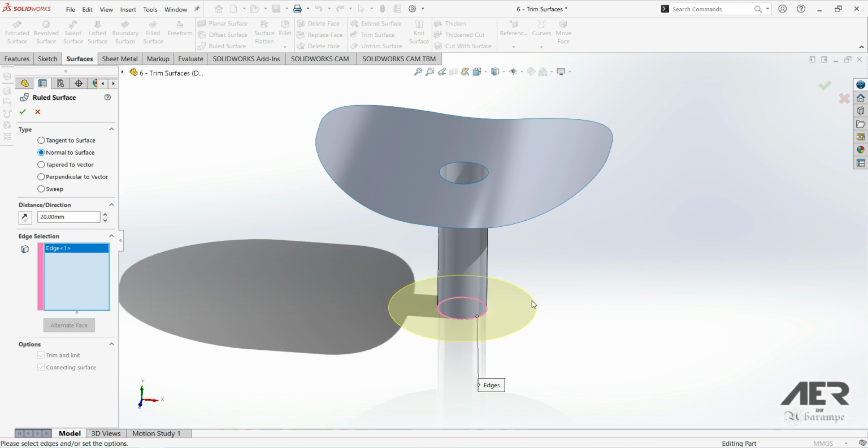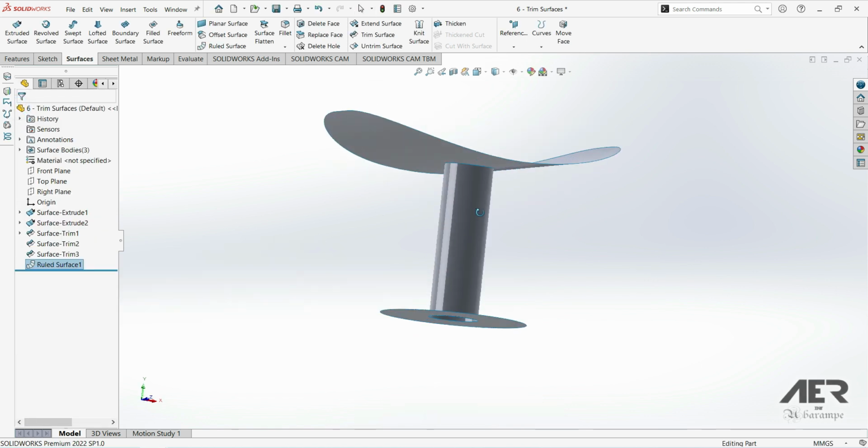And as we can see, now we flipped the surface 90 degrees. So it's now normal or perpendicular to the edge and surface we've selected. Because this is quite a simple vertical tube, and this is quite an obvious example, this base would be pretty easy to add just using an extruded surface. But imagine if we have a really wavy base here, this tool could be quite useful in following the edge around. And if I press OK, we could just add a base like this.